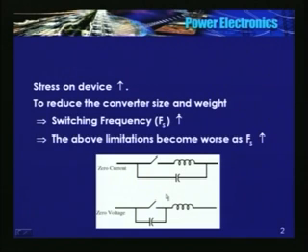Come here to the zero voltage case. Just see, I have connected a very small capacitor. We know that voltage across the capacitor cannot change instantaneously. So assume that the switch was closed. So voltage across it is approximately 0, or its saturation voltage.